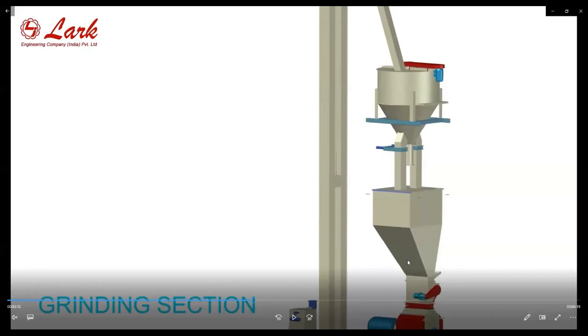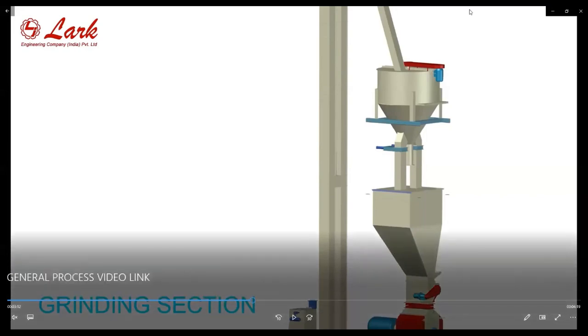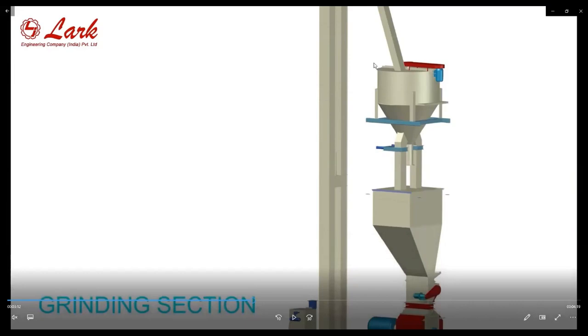So to have a good grinding, and better grinding of the fibers also, we do pre-mixing before the grinding process for just 2 minutes. This is a conventional vertical mixer with some customized changes, which we put over the hammer mill bin, that mixes the fiber and the grain equally before going to the grinding. That reduces the power consumption during grinding, and also improves the texture and reduces heat generation, because the grain absorbs the heat generated by the impact of the grinding.